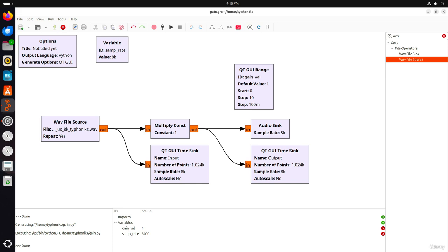So, you may ask, why do we need filters? Real world radio signals are far from clean. Instead of just the signal you want, an antenna gathers a cocktail of signals, noise, and interference. Without a filter, your receiver would struggle to isolate the desired signal from the chaos. Filters allow us to extract the desired signal by suppressing unwanted frequencies and reducing noise and interference, improving signal clarity. So filters act as a frequency gate, controlling which parts of the signal's spectrum pass through and which are blocked.